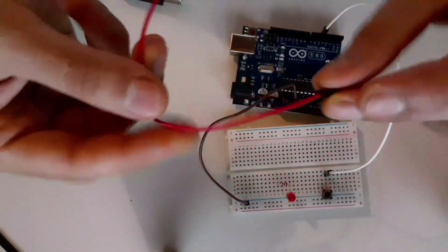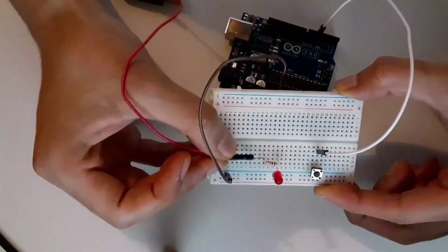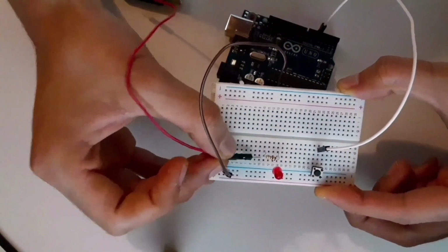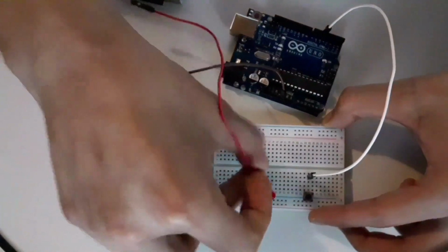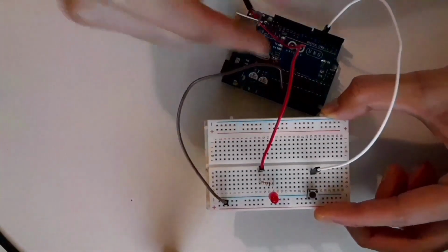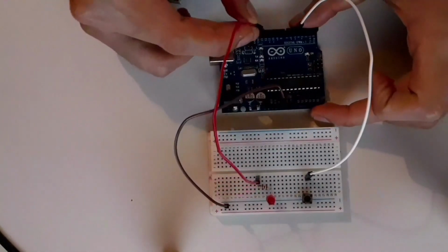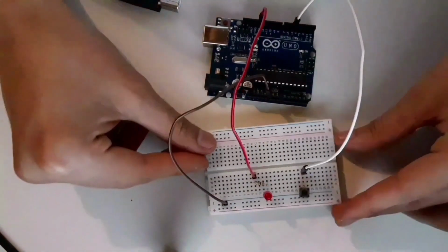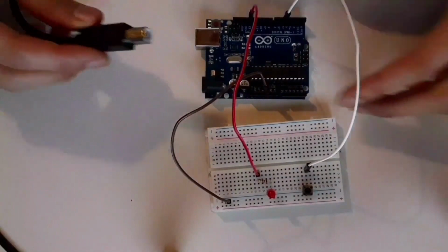Finally we are going to take the red cable. And we are going to connect it right to the resistor, where there is nothing connected, which is in row number 11. Here we will connect this cable. Ready. We have it connected there, and we will connect the other end to pin number 13 of our Arduino. Alright. So this is how the connections should remain. And now we can connect it to our laptop or computer.